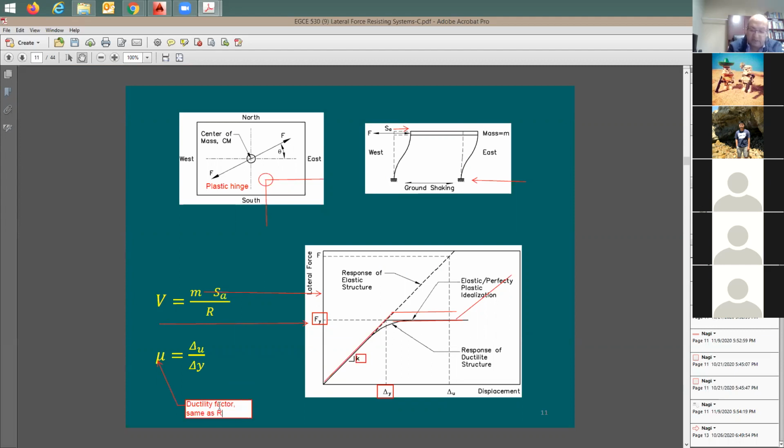I'm going to put it here, right? What is this R in the table that you use? When you calculate out the design force, you base it on our R factor of, let's say, 8, and yield strength of F sub Y, which is 50 KSI. In reality, F sub Y is going to be slightly higher.